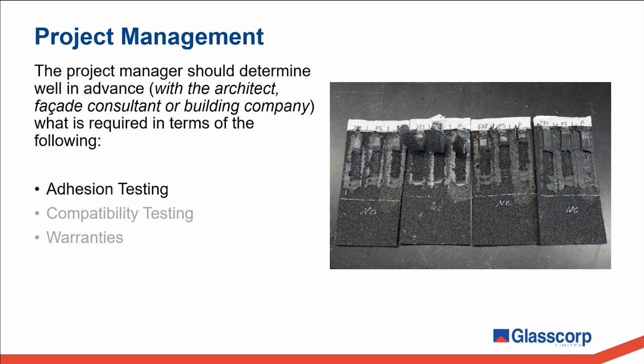To give you an idea of some of the requirements I'm talking about, adhesion testing is a big one. There may be a requirement to provide a formal lab adhesion report or a report for a sealant on a particular substrate. The photo here is from formal adhesion testing done by a supplier. If you are asked for a formal report or wish to inquire about testing for a specific substrate, feel free to get in touch with us.